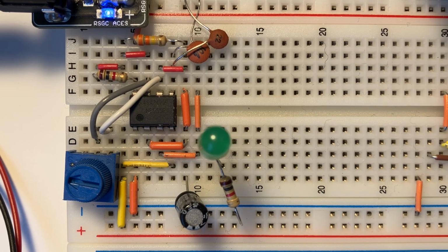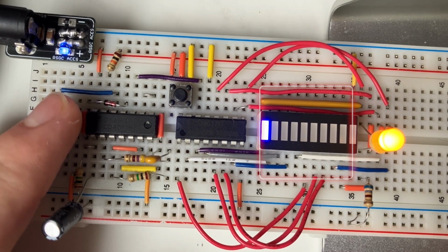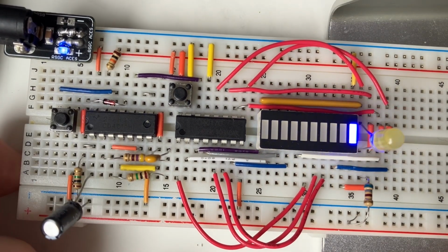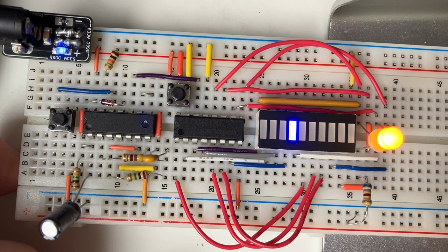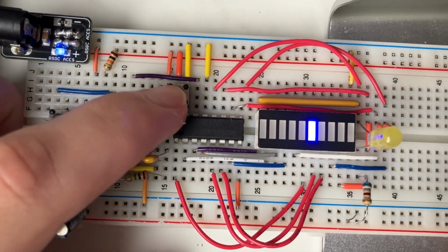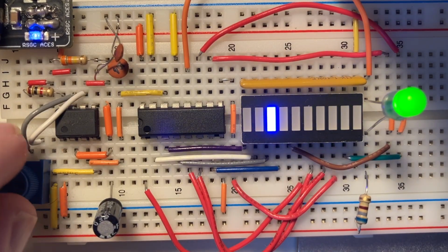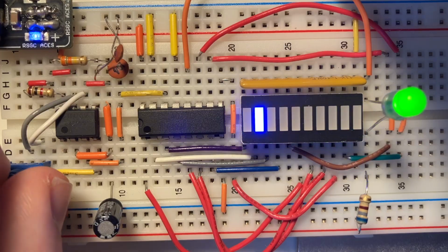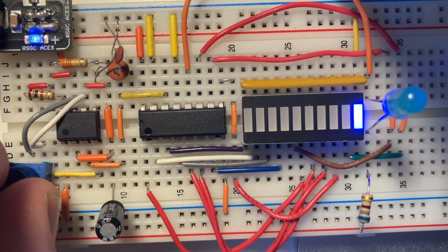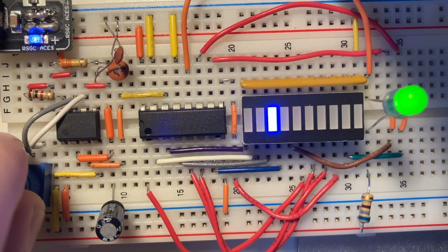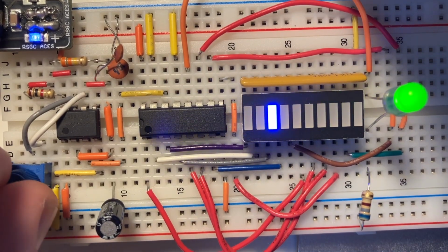The decade counter key components include the 4017 IC, an LED bar graph, as well as an LED. The 4017 uses the clock signal provided by the previous steps and puts it in sequence ranging 1 through 9 and the divided by 10. However, in the final product, only the divided by 10 is used to reduce the clock signal.